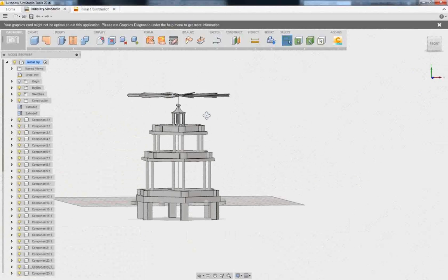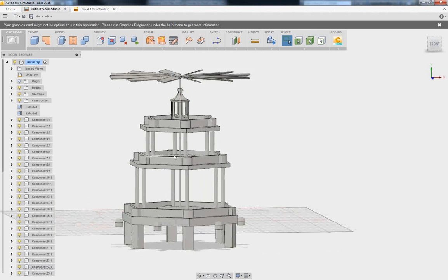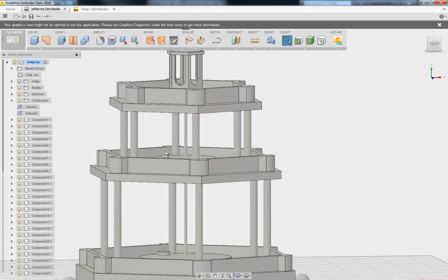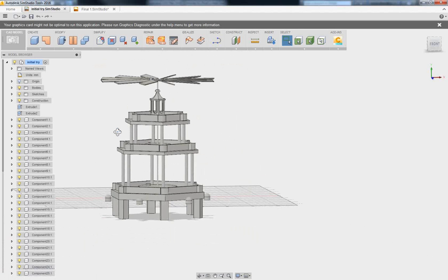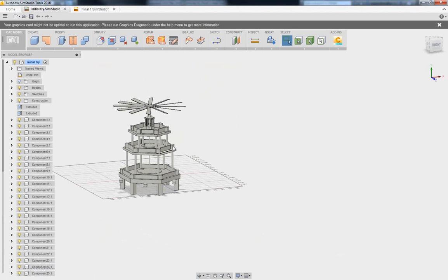And what I was hoping is I could use a simple rotating region, just make a cylinder that encapsulates just the top of my blades. And then what I found out was that because I don't have the rotating region down here, I would end up with holes in the mesh as it started to rotate. And I was like, well, that may not cause too much trouble, but I should probably do a real rotating region that encapsulates everything that's spinning. So making my rotating region became a little bit more complex.